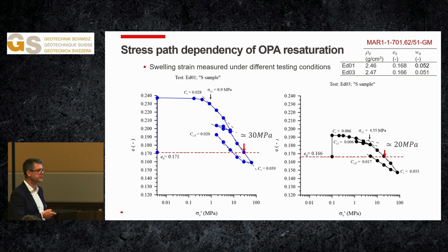But most importantly, if you would like to derive the preconsolidation stress from those curves, for example by applying the Casagrande construction, you would read effective stresses which are impossible for the history of the material. So if the swelling is allowed, essentially we are erasing almost 200 million years of history of this material, and the mechanical information that we can get from testing is quite limited.